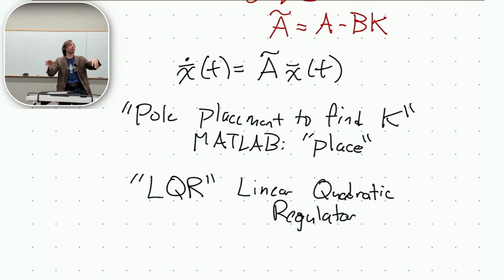All the stuff we went through, we put it into that LTI state equation, otherwise called state space form. I get an A and a B matrix. I know we didn't get the B matrix. Trust me, it's not complicated. We'll practice this on Thursday at our coding lecture. And what if you don't have a linear system? Let's say it's nonlinear. You can temporarily, locally turn it into a linear system and use the same technique.